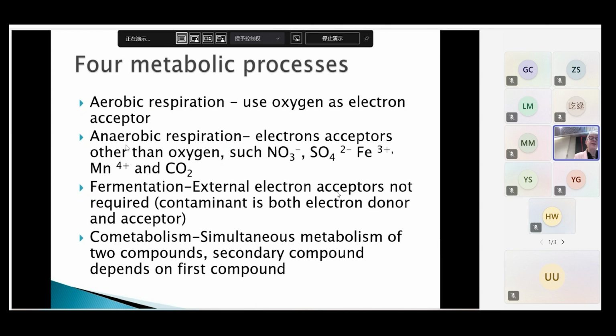You can modify the soil vapor extraction method that I mentioned before. This is the same type of setup as we did for soil vapor extraction. The difference is you use lower flow rates of air, because the whole idea is to stimulate bacterial growth as opposed to volatilization of the contaminant.